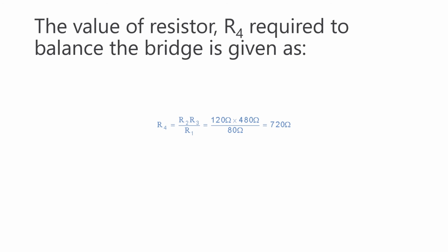The AC bridge is similar to a DC bridge except that the arms are impedances. The bridge is excited by an AC source rather than a DC source, and the galvanometer of the DC bridge is replaced by a detector. The balance detectors commonly used for AC bridges are headphones, tunable amplifier circuits, or vibration galvanometers. The source is an AC supply which supplies AC voltages at the required frequency. For high frequencies, electronic oscillators are used as the source.